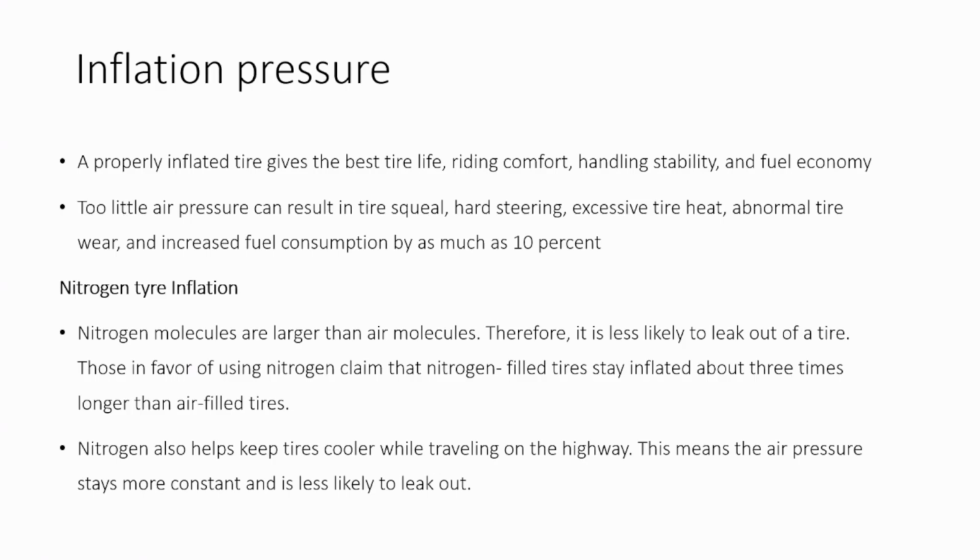So too little air pressure can result in tire squealing, and steering will be difficult, right? There will be some noises, and if the pressure is higher or lower than the recommended value, then the heat generation, the temperature of the tire will be increased, and especially the tire wear pattern will be abnormal, right?